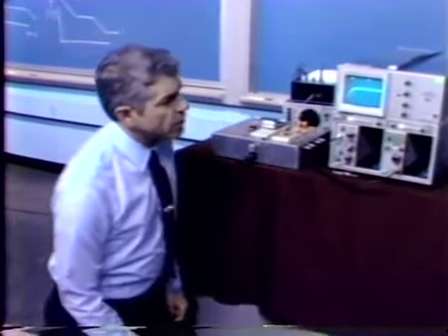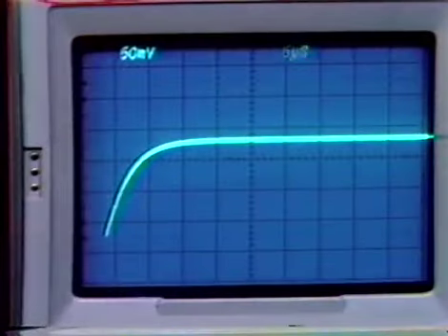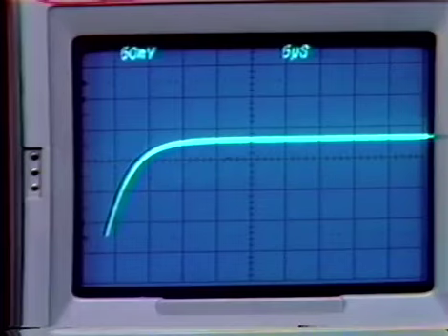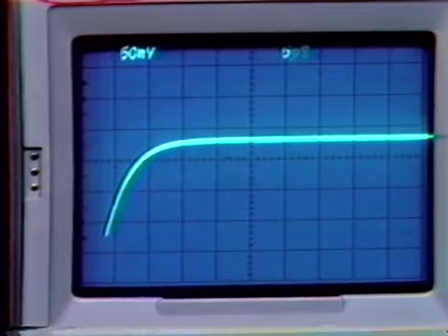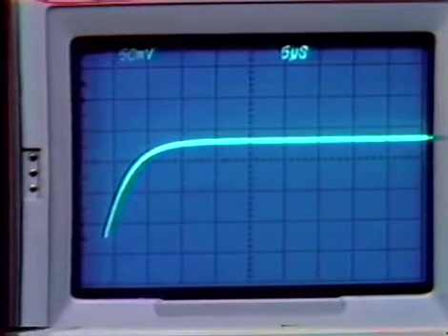And the result of that, of course, is to give us effectively an exponential kind of response. We'd expect, when our loop is rolling off as proportional to 1 over S, a first order system. We've chosen numbers so the crossover in the loop occurs well below any additional phase shifts associated with the amplifier itself. So we get a response that looks very, very nearly first order.